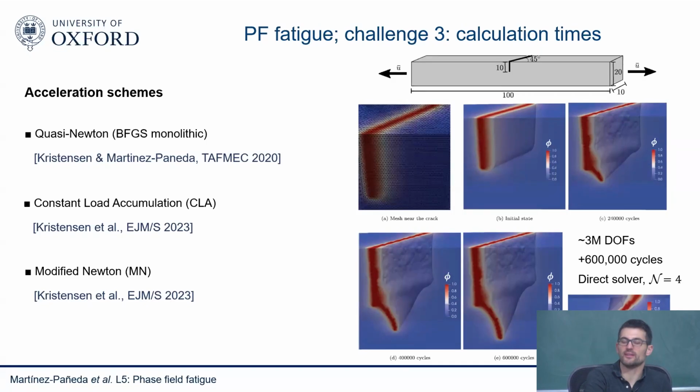So far I've only been talking about linear elasticity because we're dealing with very high cycle fatigue or small scale yielding. I have some slides on plasticity. That's an even more tricky question. For the time being, we seem to be able to get good agreement with experiments. We've done mostly low cycle fatigue, plasticity, and so on. You need a proper nonlinear constitutive model, Chaboche style, so nonlinear kinematic hardening, nonlinear isotropic hardening, and so on. But once you incorporate that, then you have a fatigue degradation function, and that seems to be enough. So you do see the kind of cyclic behavior that you expect. You do see the drop in S-N curves and so on.